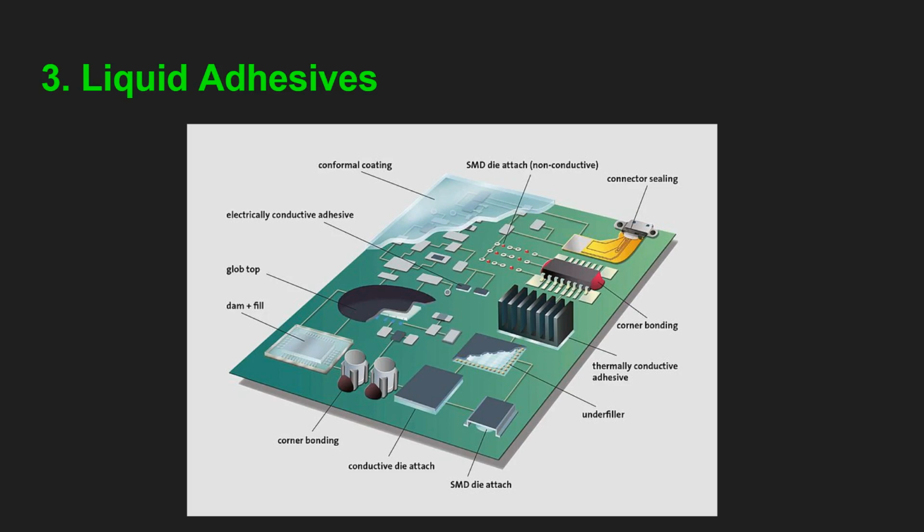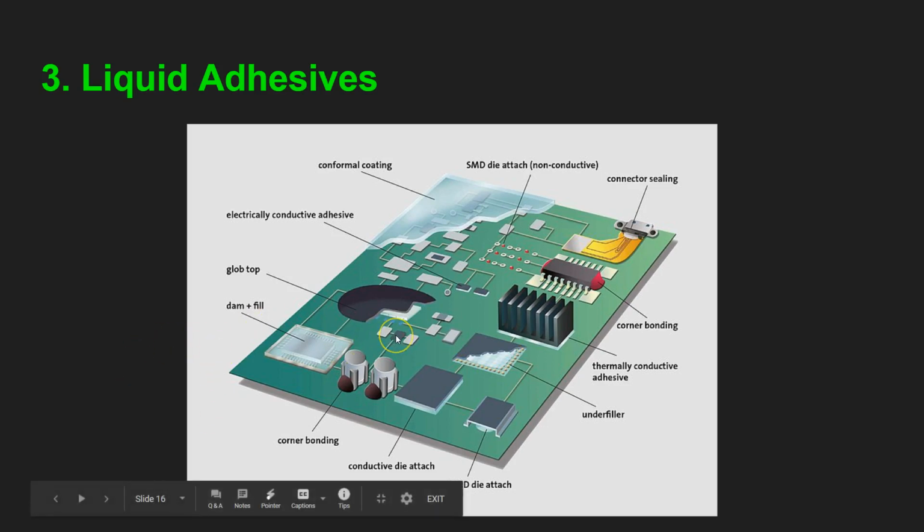As you know, the continuing trend towards making the PCB and the components smaller presents the challenge of ensuring that, despite their ever decreasing size, contacts and components continue to work reliably. Many solder joints on PCBs are therefore being replaced with more flexible electrically conductive adhesives.